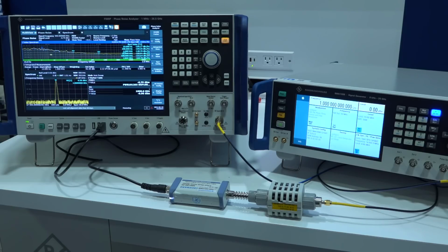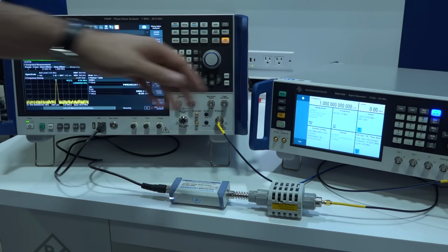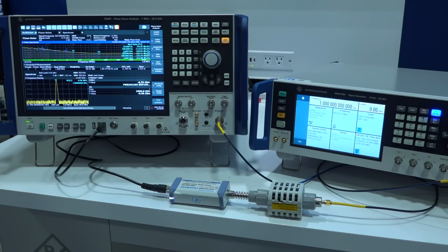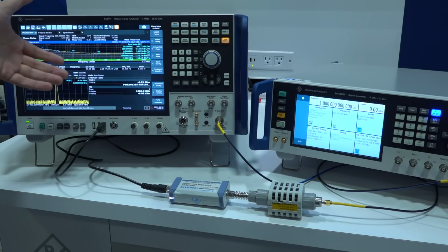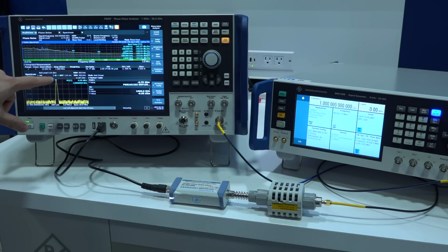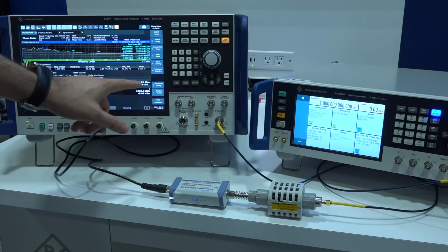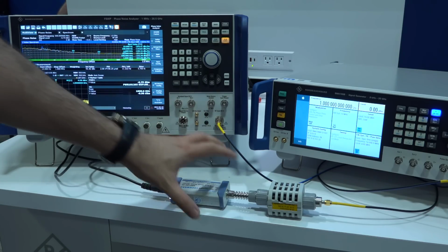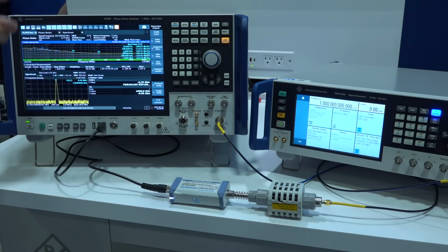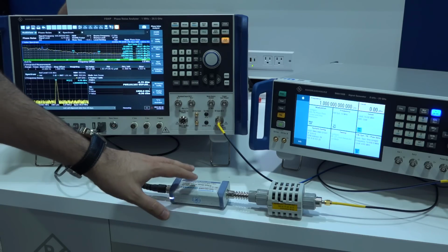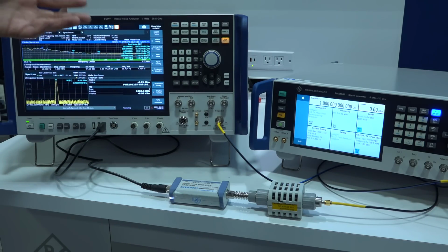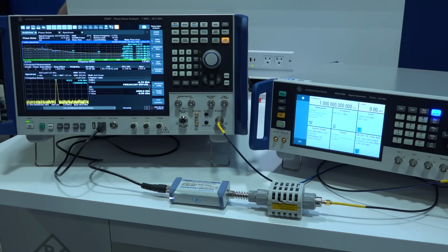So it's essentially extending the capability of the FSW all the way to 170 gigahertz, even for noise figure, which is pretty helpful. And here we have the combination of the SMA100B, but of course the FSWP, one of the most capable spectrum analyzer phase noise analyzers on the market. Now, because this is a full-fledged spectrum analyzer at the same time, you get complete spectrum information, you get cross-correlation, phase noise, and everything that comes with the FSW. But now there's also the ability to connect all the power sensors directly onto this. So in one setup, with your power measurements, you're getting spectrum information, cross-correlation phase noise measurement, extremely precise power measurement all together. So it becomes a single station for characterizing high-performance oscillators.